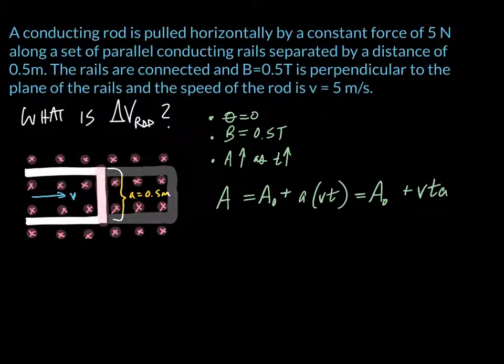And so we are going to need dA/dt because that's the only thing that's changing. So we're going to be using the form of the equation. Let's see, I should have wrote that here. So induced voltage is going to be minus B cosine theta dA/dt.